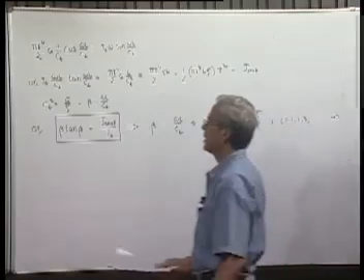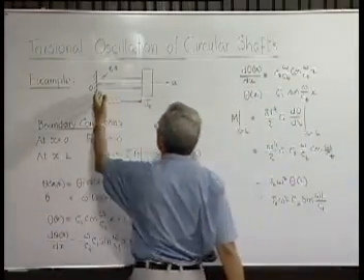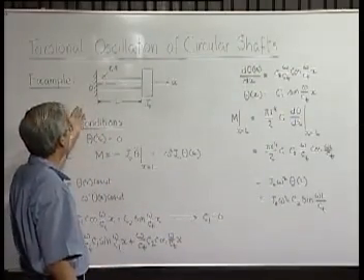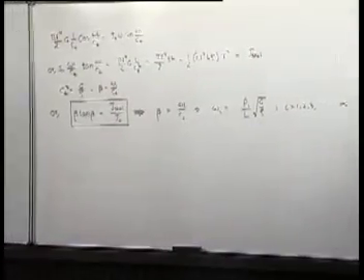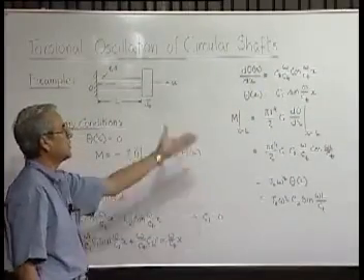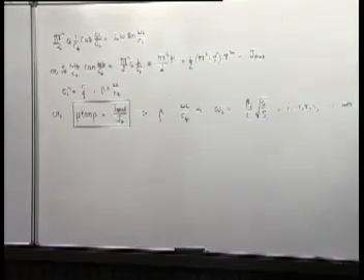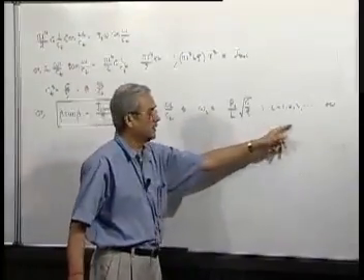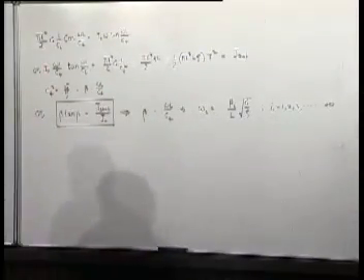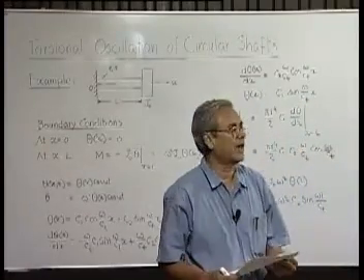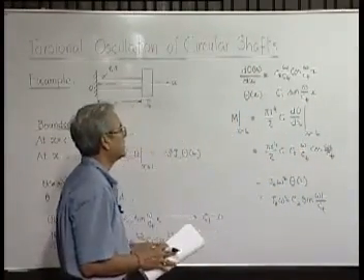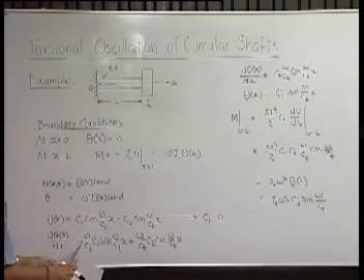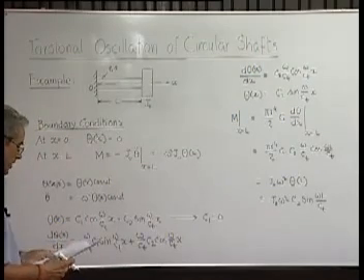So there can be another problem in which both sides of a shaft carry two disks, one with J1 moment of inertia, other side with J2, and the shaft dimensions are given, material is prescribed. We can find out again the equation, that means a transcendental equation we will get, and again solving which we will get ultimately the natural frequency. So thus we find that torsional vibration of shafts are very similar in its form and general form of solution also, and equation of motion also, as in the case of longitudinal vibration of bars.